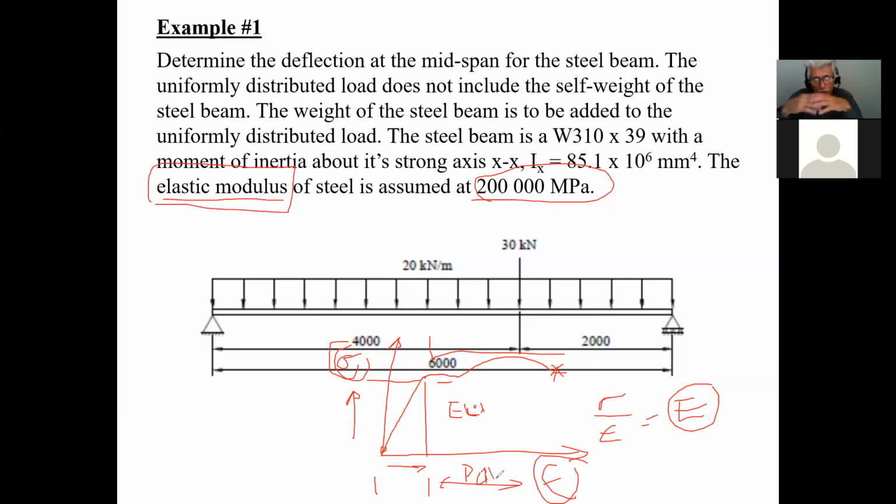Plastic range means that deformations will occur, and if you remove the load before it collapses, whatever deformations it incurred in that range will stay permanently deformed. Part of it will come back, but a lot of it will stay deformed. And what happens here is that when you get past the yield point, what they're showing you here is that as you add less stress, you get lots of deformation. In other words, the material starts to stretch, starts to become almost like plastic. So it's going to be very, very stretchy, with big deformations.